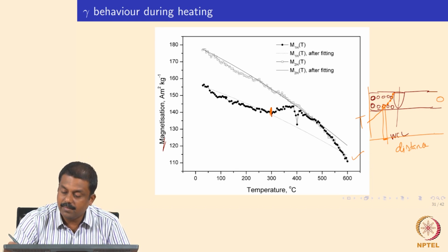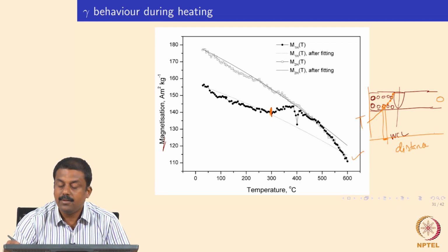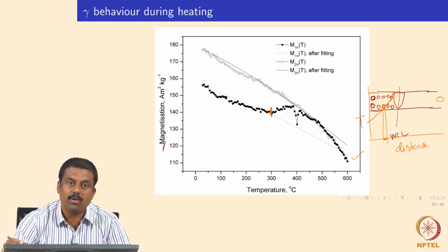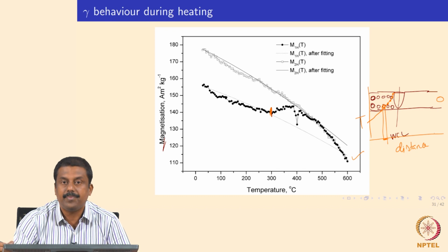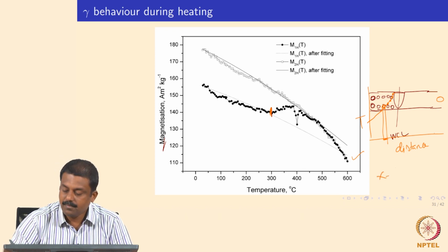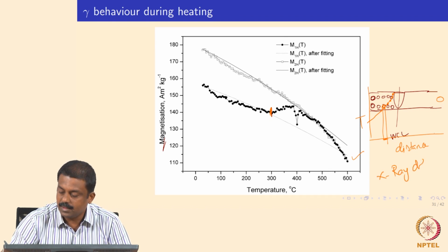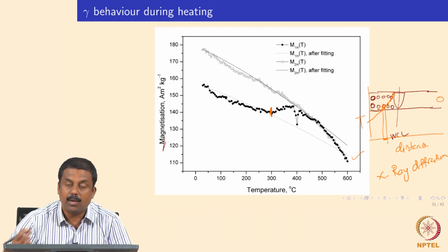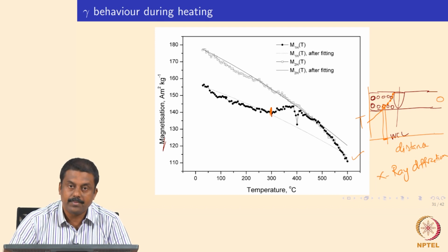So in order to have very refined measurements, we will have to go for other techniques to measure retained austenite. One such technique which can be used to measure the retained austenite at very local regions in the weld zone is X-ray diffraction. X-ray diffraction is another technique which can very effectively be used to measure the amount of phases that are present in the microstructure.